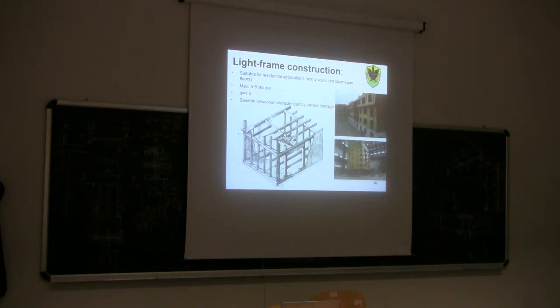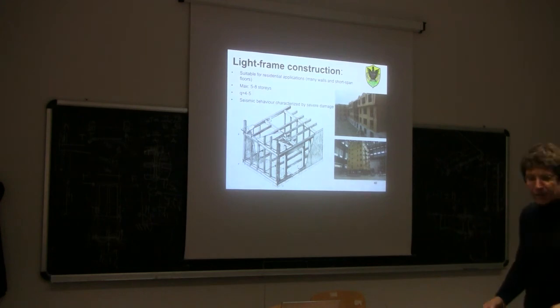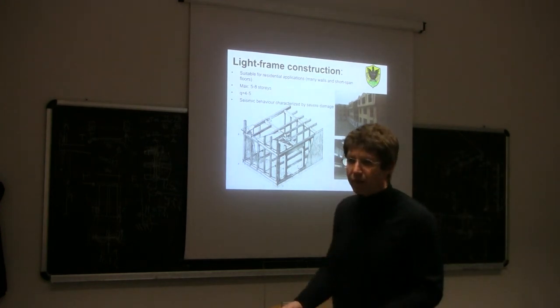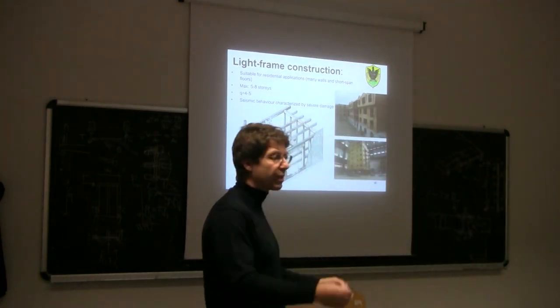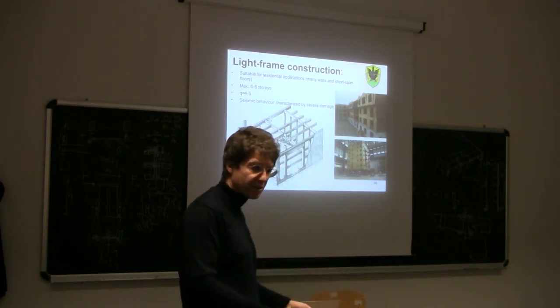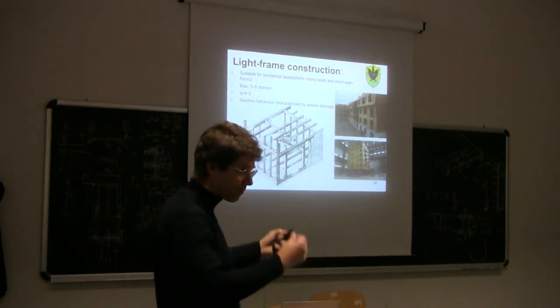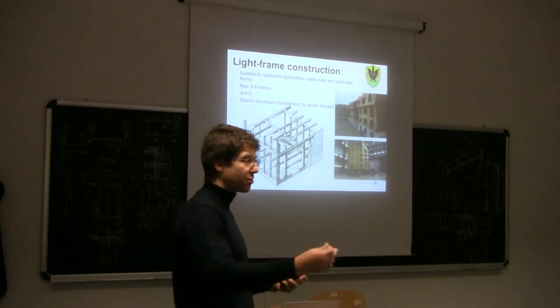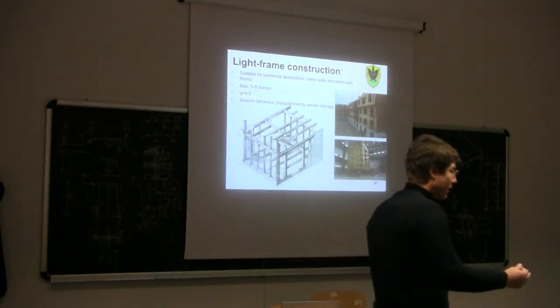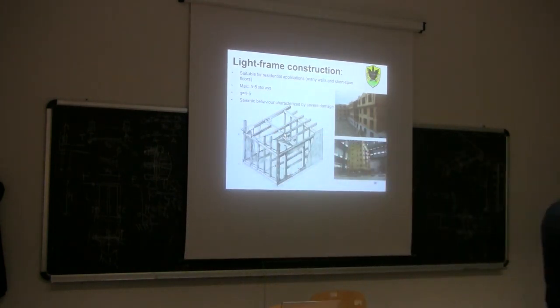And of course, if you use such a high value of the behavior factor, you accept that if there is a strong earthquake, hopefully nobody will die if we have designed well, but in the end it's very likely we will have to pull down the building, because it will be characterized by high, severe damage. So 4 or 5 means that it's going to plasticize a lot, and at the end of the earthquake it is probably going to be completely tilted, okay?